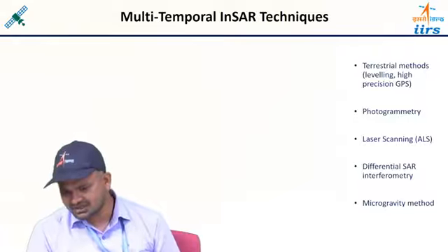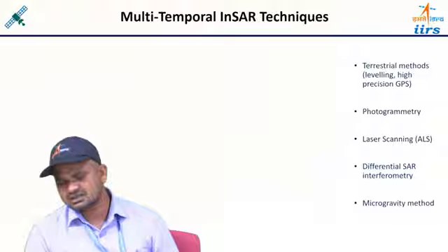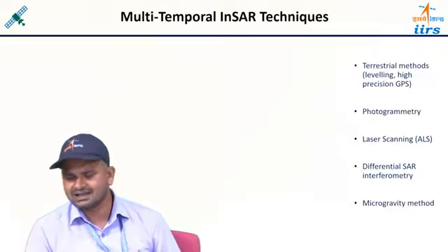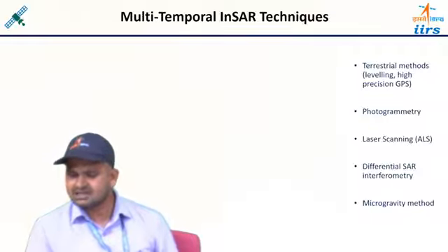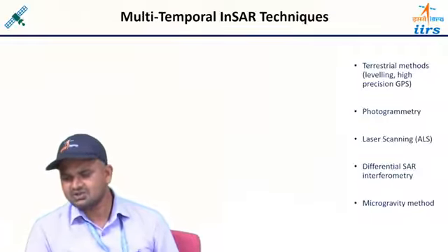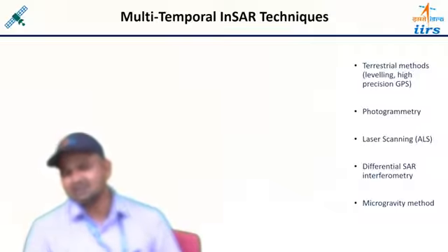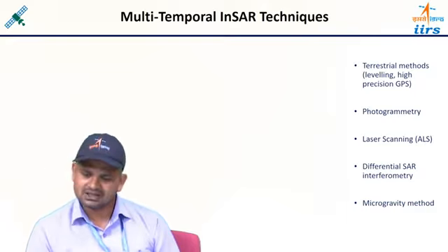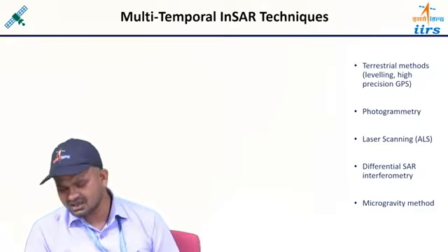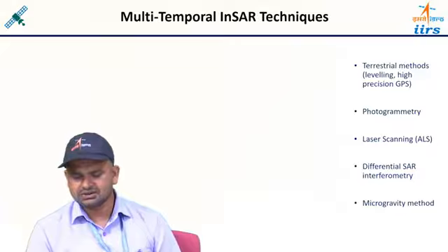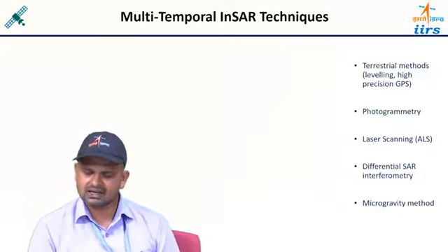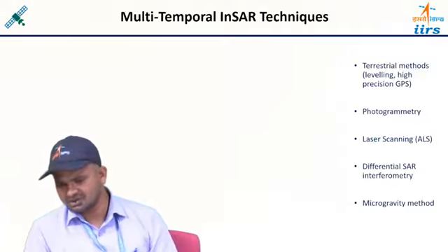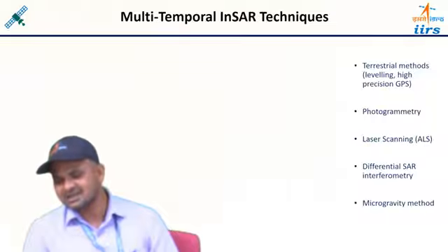But these point techniques have certain limitations, because of the leveling equipment we generally use in surveying. Surveying means you are going into the field, collecting the data sets. So the survey itself is a very costly affair, and the frequency of observation is also very limited, and whatever you are observing is again point data. So that is not basically serving our purpose. And surveying you can do over a small area. If you want to do such investigations over a large area, let us say continent-wise or global investigations, it is almost impossible using leveling equipment or surveying techniques.